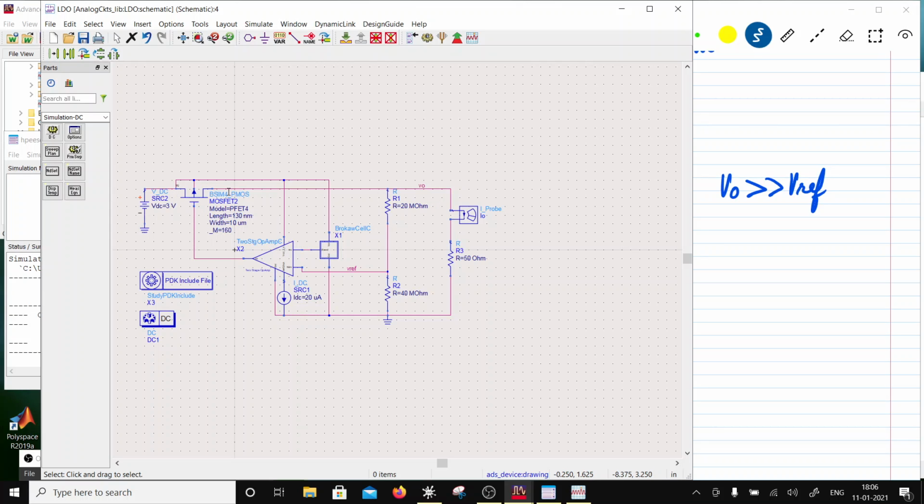Now will the two powers be the same? No, because when the current is high, the overdrive here is high. So the transistor will be dropping that overdrive across it, right? As the current is high, the overdrive is high. That means it can deliver lower power when you have a VO as high. If VO is low, it is capable of more current. That means the overdrive is going to be large, so dropout is going to be large, right? So that's how it works. So now the two powers should almost be the same, but they will be slightly different, right?